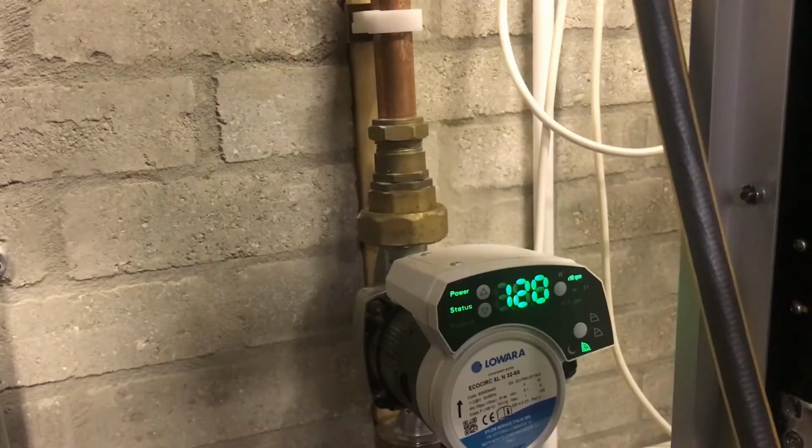When you leave the pump for a period of time, if it goes completely off, when you switch it back on, it will go through a 4-stage degassing sequence, which essentially runs the pump backwards and forwards to try and dislodge locked air, which tends to gather actually around the impeller, and eject that from the system. And once it does that process, it will go to the lowest speed, and you can wind it all the way up to 360 RPM. When it's been left for a little while,